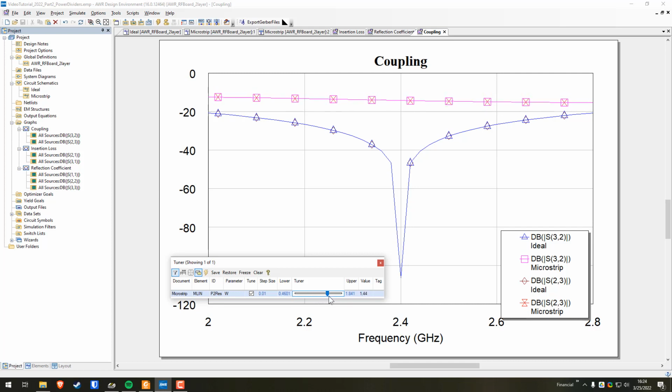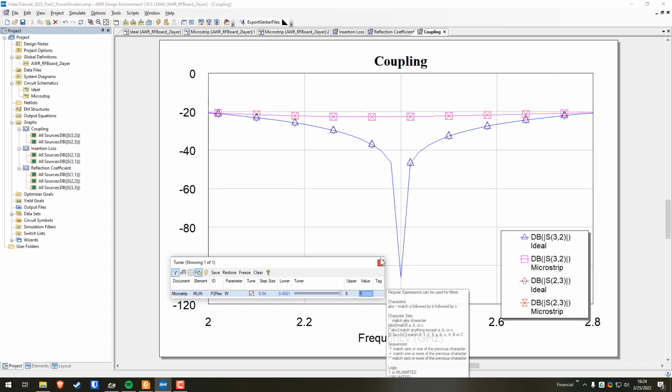So as you make the line thicker, you reduce the impedance of the line looking in, right? So that's basically the resistance kind of goes down, right? So as we decrease the resistance there, we can see the line dropping more and more and more. But now I'm curious, right? Let's set the upper limit to like 5. Some absurd width, right? And then we'll say 3. Okay, so it just keeps going down. 5, it keeps going down.